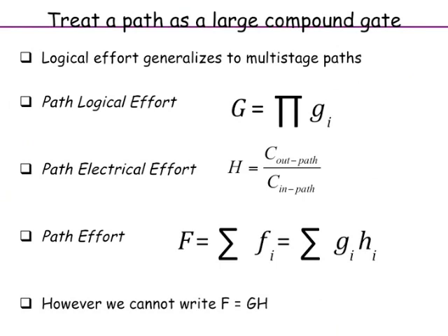But when you do custom circuit design, maybe for a processor, where a lot of the custom circuit design is done, that's where the designers themselves have to figure out the sizes for the transistors. So that's when you use these concepts to come up with the sizing, at least the initial sizing, and then you can give it to an optimizer to do final fine tuning.